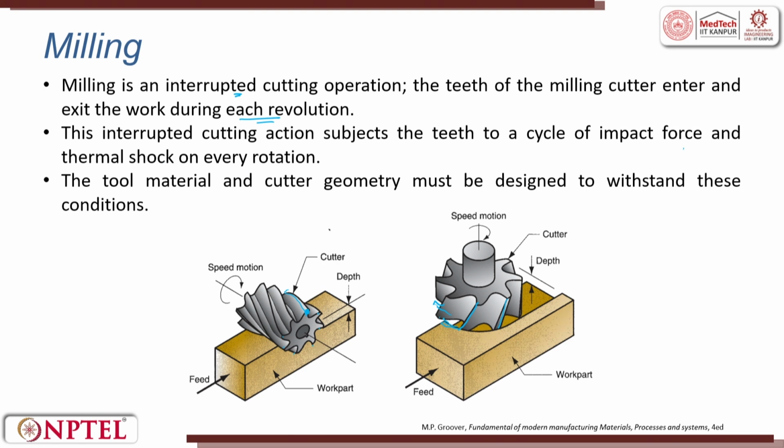Why is there thermal shock? There is a friction phenomenon between the metal workpiece and the cutter. In a single point cutting tool, the tool edge was continuously in contact. Here, after it enters, it exits. So, there is going to be a discontinuous contact.